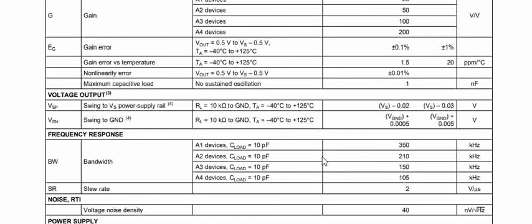So again, you don't find a clear calculation in the data sheets. Most of the engineers take it by experience. For example, if you want to use this entire bandwidth of 350 kilohertz for this particular device, you have to have a load of 10 pF. If you have a load of 100 pF, this may not be applicable. The actual bandwidth coverage could be much lesser.